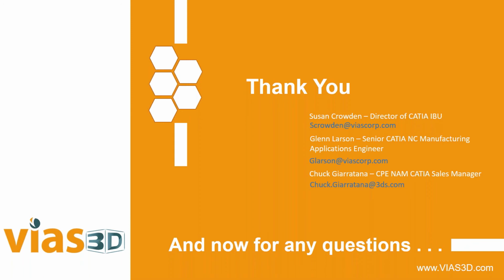We have another one that says, for the relational automation, is the coding done in CATIA or using any other script language? Yeah, actually, you can use just about any script language you want. You can use Visual Basic, you can use C++, just about any language you have access to, because you can run a command prompt, or you can run just a script in a notepad. So anything that you can pretty much write is usable up here on the 3DEXPERIENCE platform.